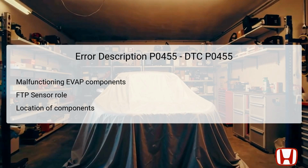The FTP sensor, located on the top of the fuel tank, continuously monitors changes in fuel tank pressure to identify leaks. If the pressure readings deviate from expected values, it signals the PCM to engage the diagnostic routines, leading to the P0455 code being triggered.